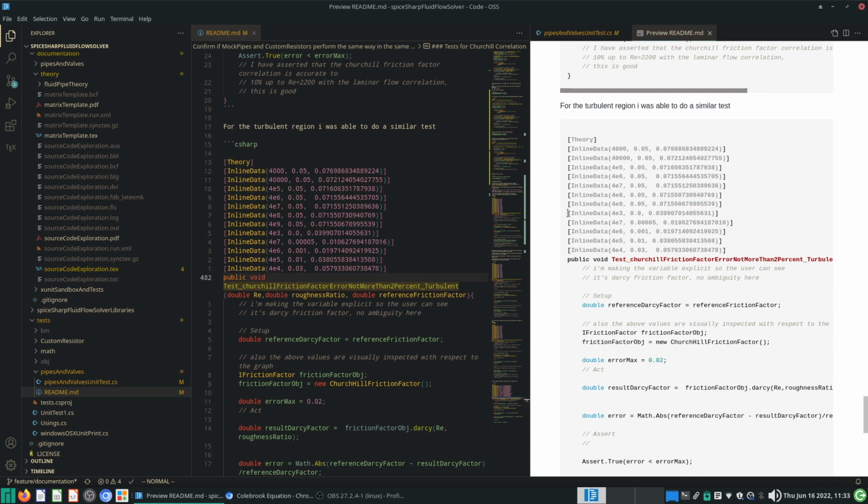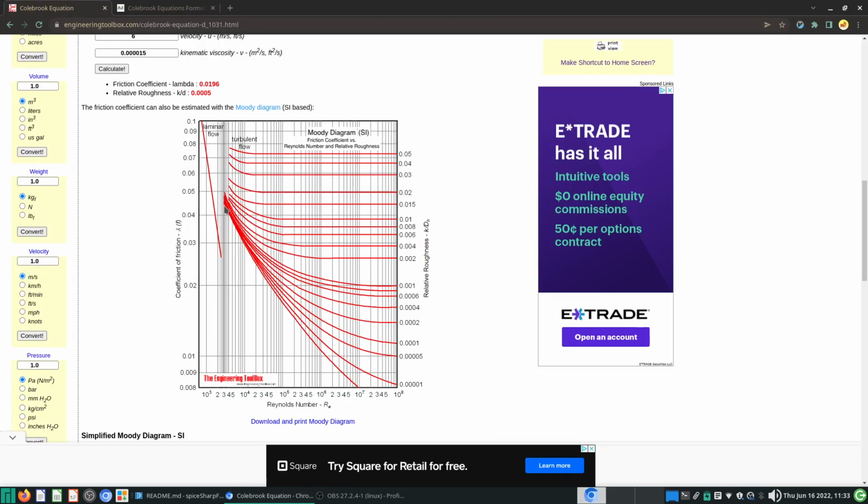And then what do I do next? I want to look at the smoother part of the pipe. So I just go straight for zero roughness at all. Zero roughness will be somewhere here. You can see the friction factor is somewhere in between 0.04 and 0.05. So this is the other extreme. And the other extreme is here.